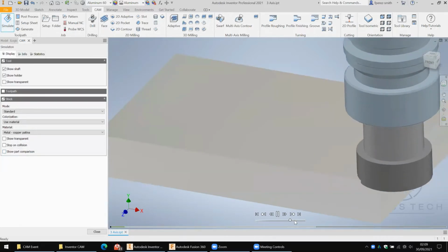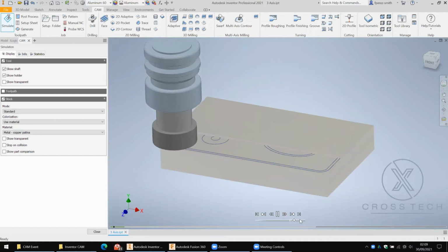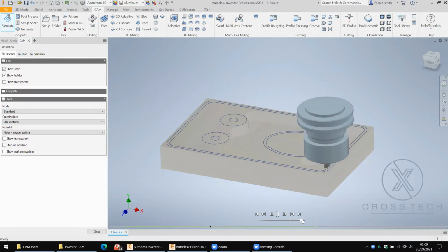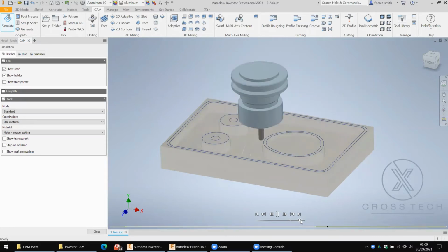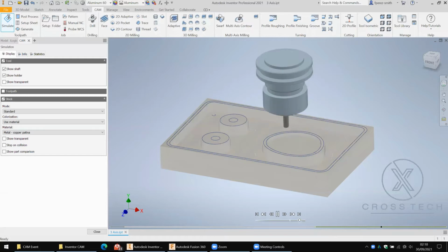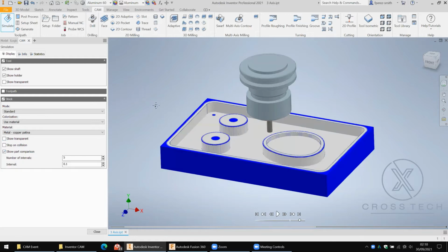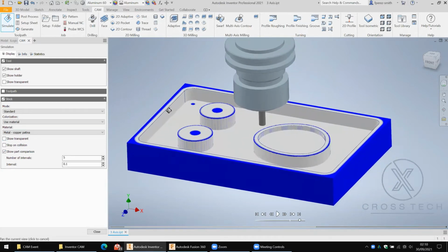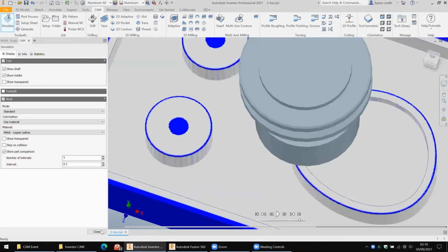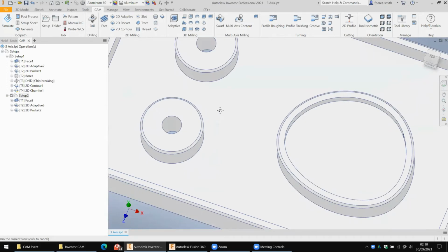That's it. Wonderful. So we've got our facing operation coming in here. We have adaptive clearing, which rapidly removes material using a trochoidal operation. And then we have our finishing pass using a pocketing operation, which should leave a nice finish on there. And by turning on part comparison, we can see that the material in blue is a material yet to be cut. So as we can see, we've got 4 holes in the corner, 2 bore holes, and some chamfers to cut out. Easy. Next, we'll come along and we will add a boring operation.